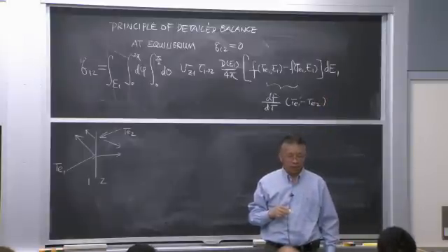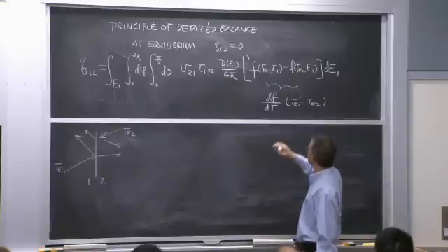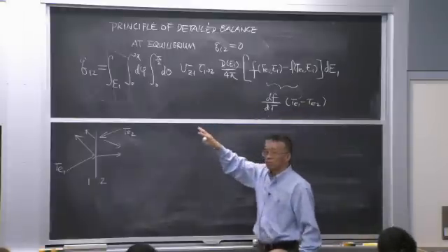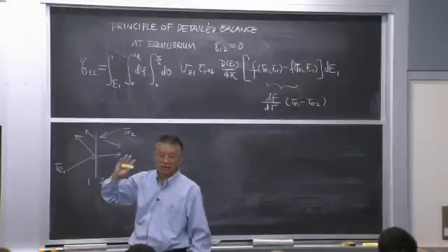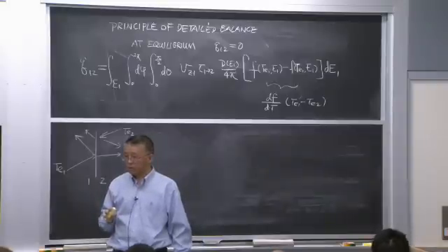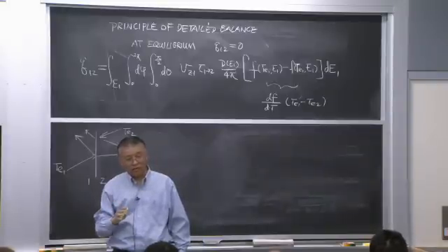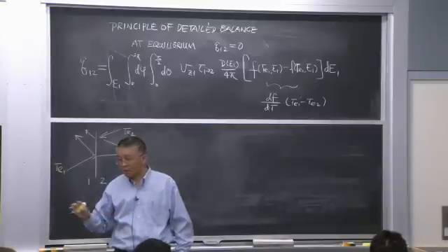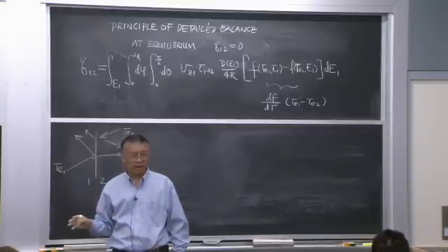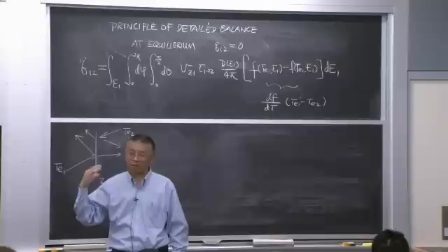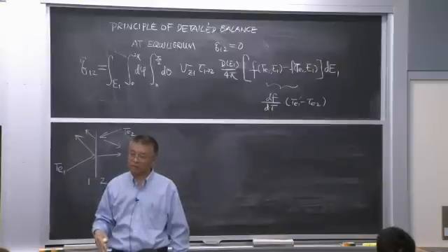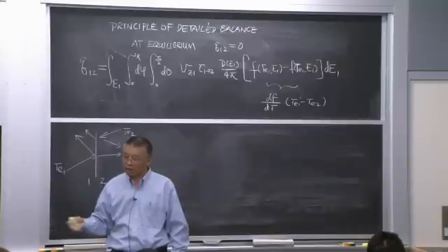And delta T over Q is defined as the thermal boundary resistance. So if I have a boundary, I have reflection, I will get a resistance. And it's the same for any material. If you have charge reflection, you get an electrical resistance. If you have photon reflection, you get thermal resistance.